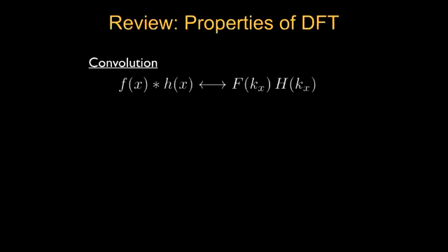Okay, before going to the details, I'll simply cover some simple math on the Fourier transform relationships. Whenever you have a convolution, when you apply the Fourier transform, it becomes multiplication. That's a simple thing, but you're going to encounter it in many situations, so you have to memorize it. Convolution becomes multiplication, multiplication becomes convolution.